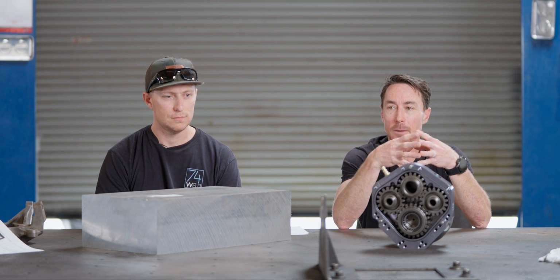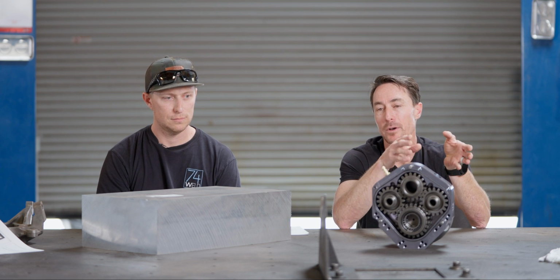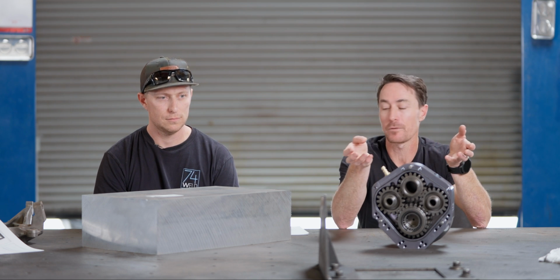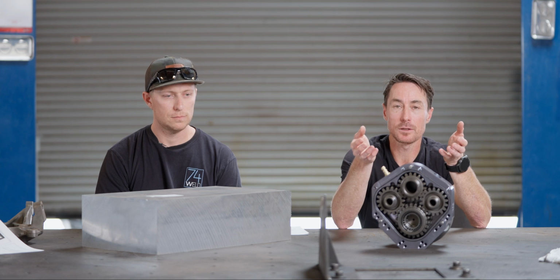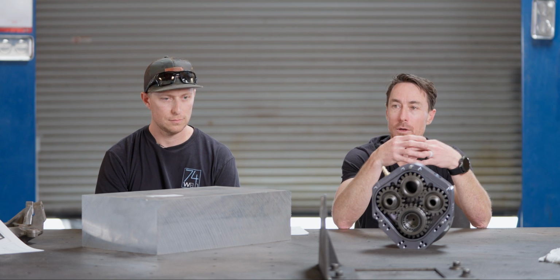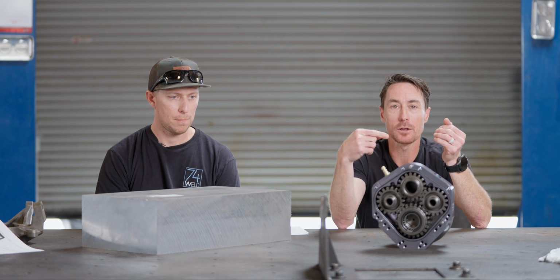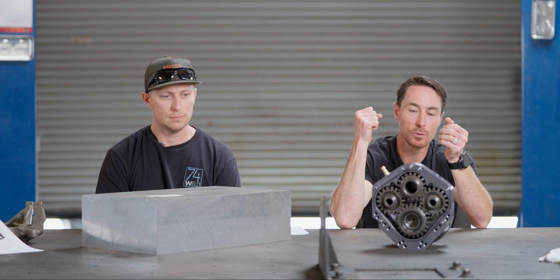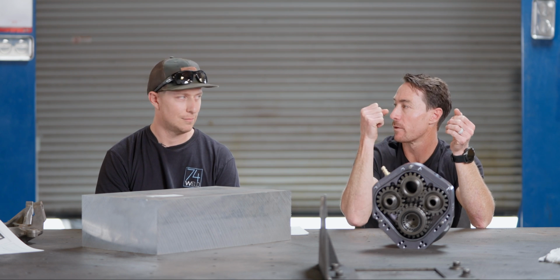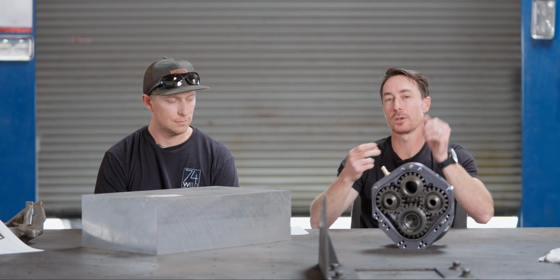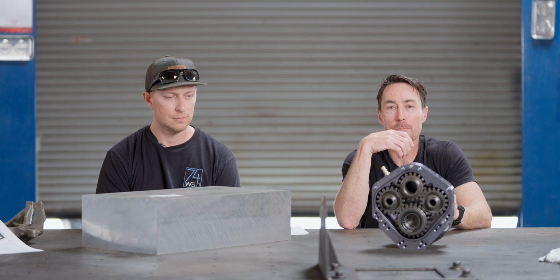300M is a modified version of 4340, and it has a tendency to work harden. So if you cut threads in a 300M wheel stud and you run that impact over that lug over and over again, you'll end up work hardening the material.